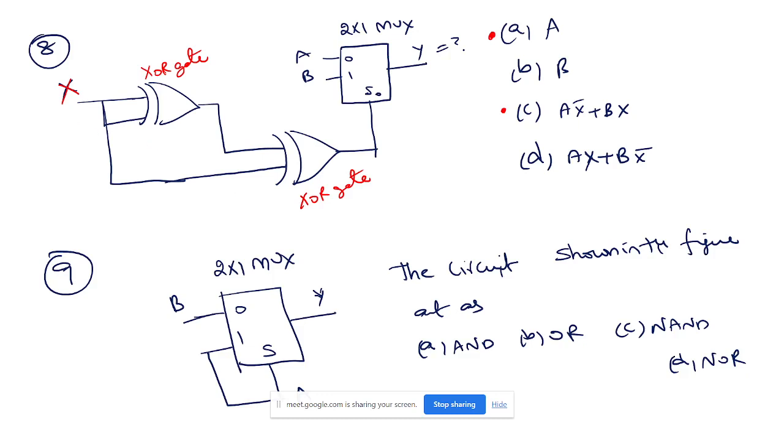So what is the XOR operation? Let's say, for example, A complement B plus A B complement. Both the inputs are X only. X complement X plus X X complement, which means this is 0, this is 0, this is 0. So what is the output of this? 0 complement X plus 0 X complement. Correct? 0 complement is 1, so 1 and X plus 0 is 0 into something is 0. So this is X. So S0 is X.